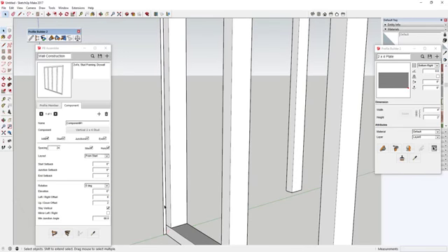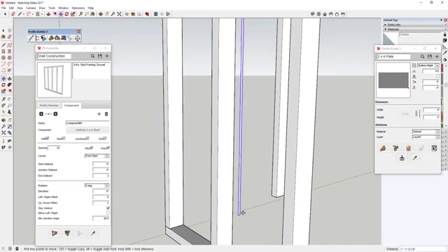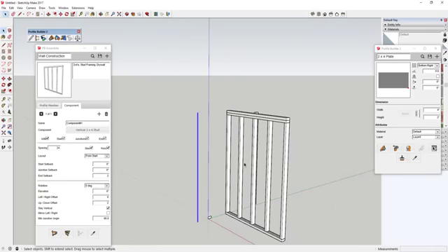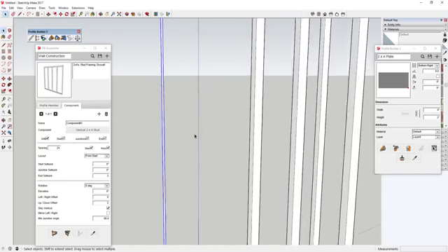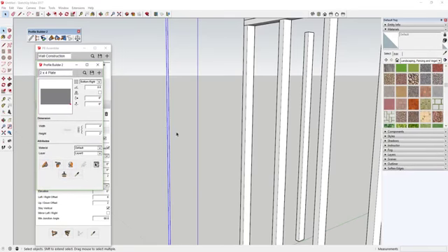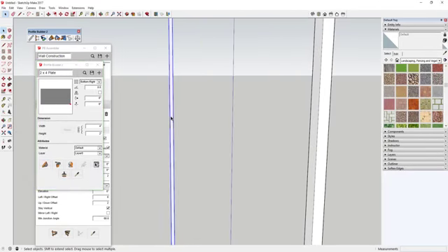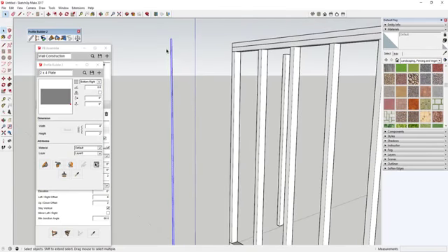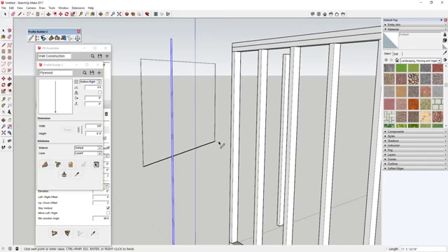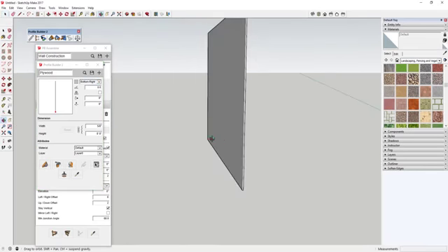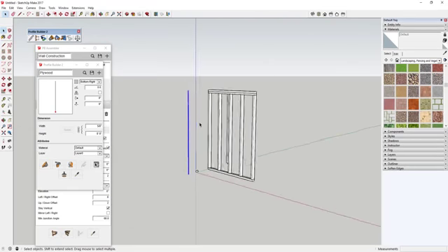Then we'll close it just like this. We'll go ahead and move it out of the way for now. I was just using that wall as a guide point right there. And so what we're going to do is add a profile for this. All that means is you're going to double click to select this little 3/4 or 5/8 inch object that you drew, and then just click add. We'll call this plywood and hit OK. And again, we're going to set this to the bottom right. So now if you draw this, you can see it's going to create a 5/8 inch sheet object right here.